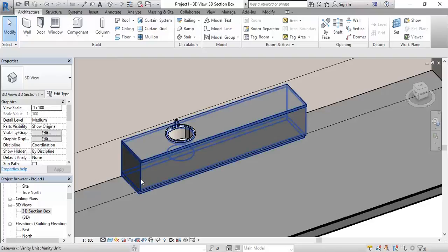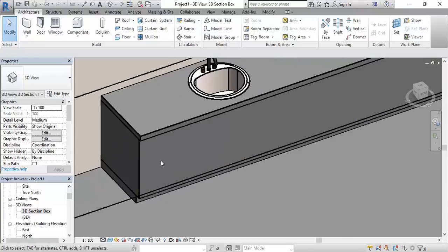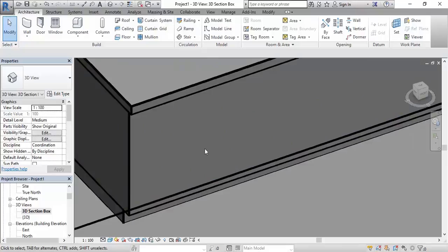You might be thinking you've got to make it by extruding lots of things from the plan. But think about something like a shoji screen or that lattice pattern. And you might realise that you can make it more easily with an extrusion by drawing on the surface of the unit. So in other words, I can extrude from this door face and essentially extrude sideways instead of extruding up from the plan. And if you think about all of the building elements that you can make by either extruding from the plan or extruding in a different direction, you probably realise that, like I said, nearly everything in a building can be made just using extrusions.